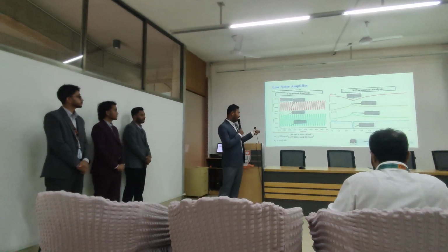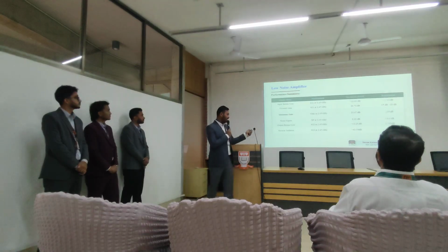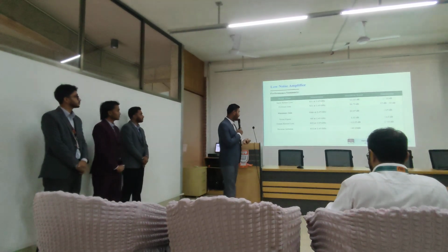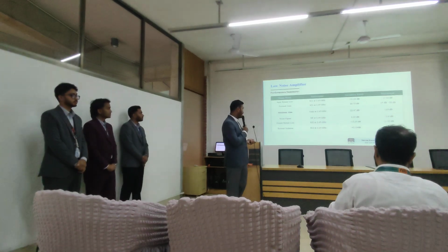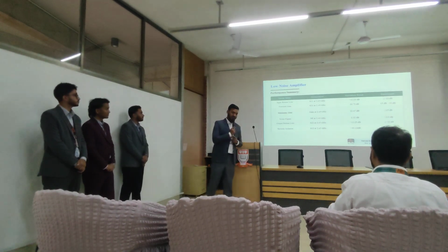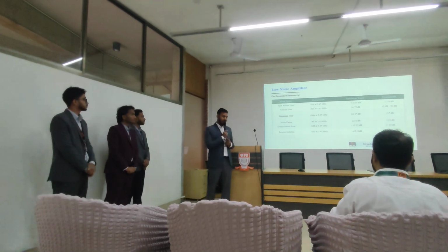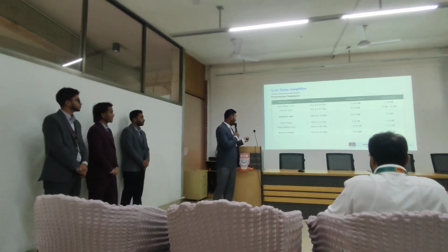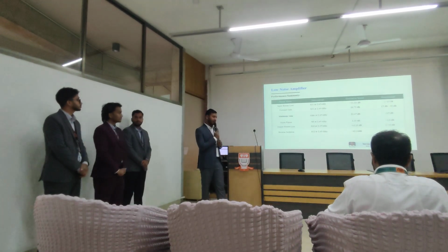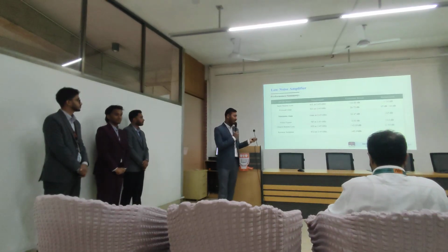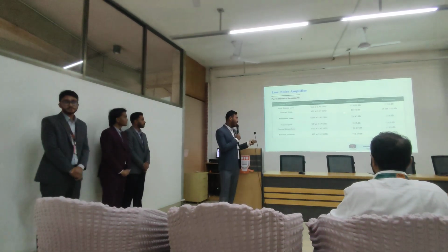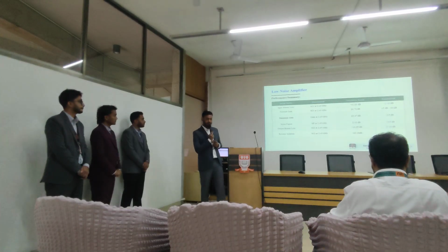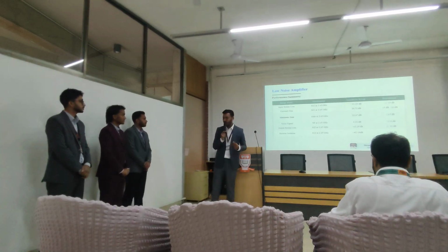And moving to the performance summary slide, here is our complete result for the LNA. It shows the simulation results meet our requirements, such as gain, which we targeted at 15 to 20 dB and we get a 20 dB result, and then the S parameter analysis, S11 and S22 and other parameters, which also fulfill our requirements. Now I request our teammate to continue with the next part.